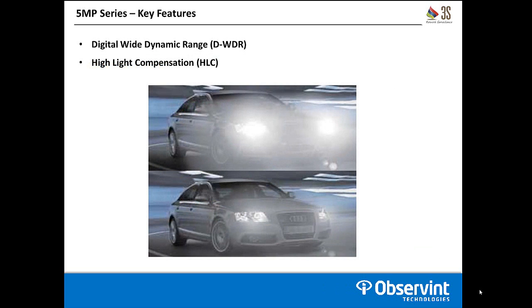There's an additional highlight compensation feature in these models that will help out for when you're just worried about backlight coming into the camera. So a good example shown here is the headlights of a car. This doesn't mask the light out, but it will actually help suppress that light quite a bit to make sure that you're not going to get a fully exposed shot and get nothing but a white image in the camera as it tries to stream that out.